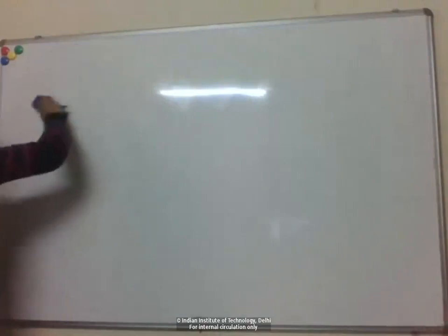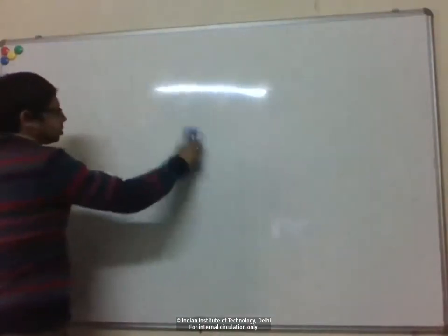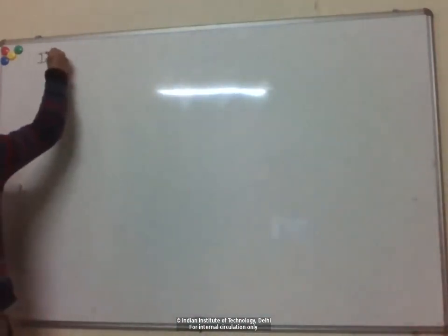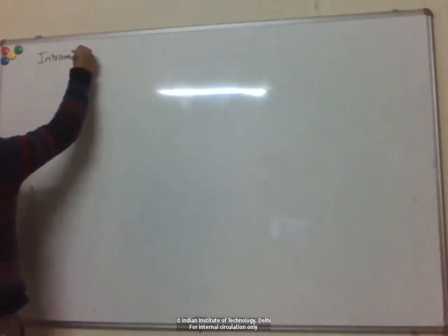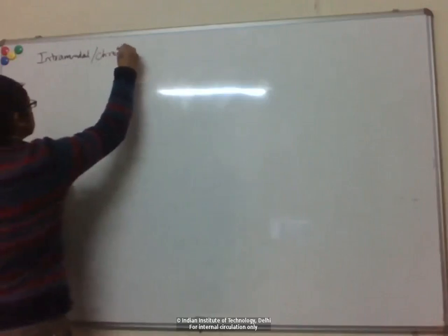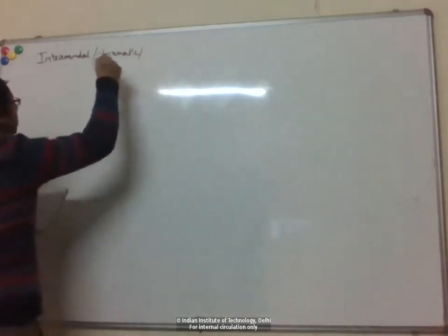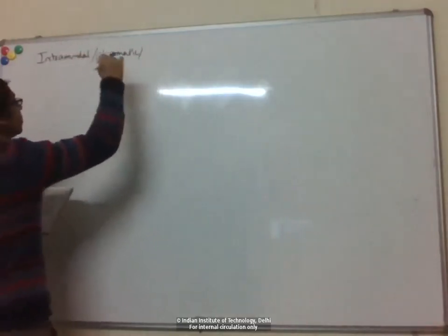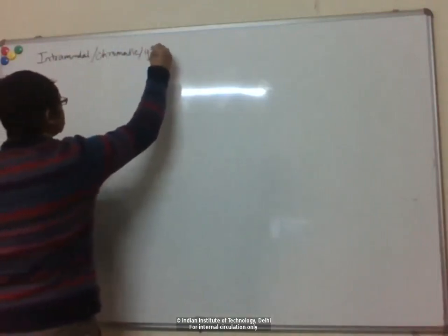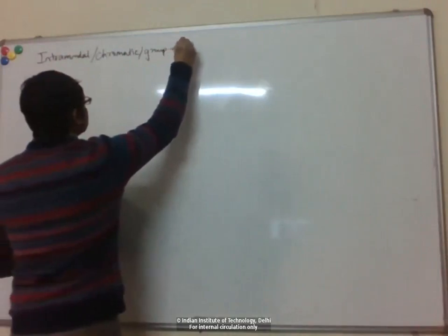But for long haul systems, we moved exclusively to single mode fibers. Okay, so the dispersion mechanism here is intramodal because there is only one mode. Chromatic because it comes from the spread in frequencies, or different frequencies traveling at different speeds, or group velocity.